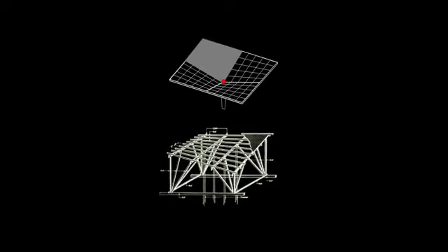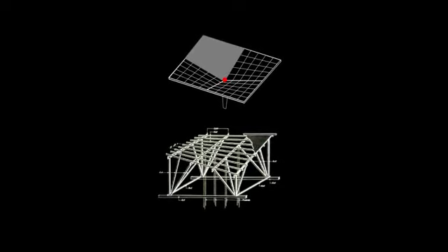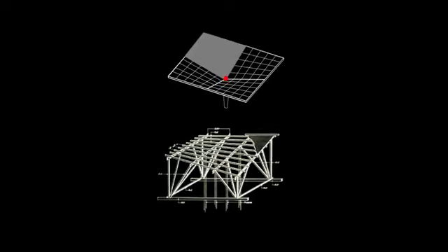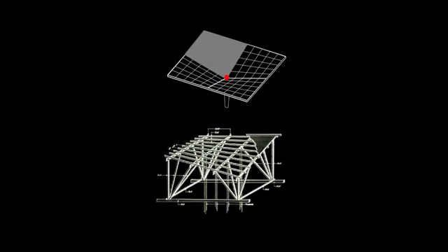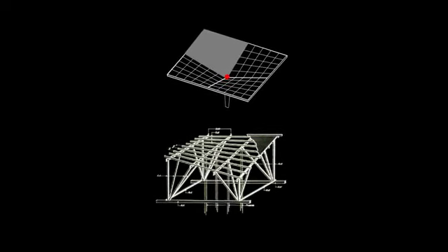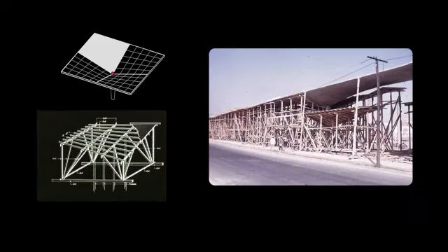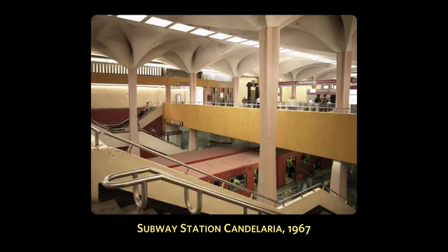Each set of forms was essentially 1 quadrant of the umbrella shape. So the shaded part of the sketch represents the straight line pieces of wood that you see below that sketch, representing the formwork used to essentially shape that umbrella. And on the right, you see an image of one of those pieces of formwork being lowered since the concrete had hardened.